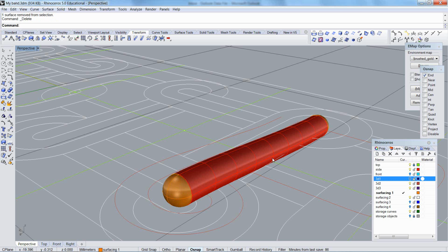That's a good trick to use, guys. When you have an object like that and you just want to keep one piece, explode it, then take out the one piece that you want to keep using control click, and the rest will remain selected, so you can just hit delete. That way I don't have to go click, click, and delete. The command of explode left them selected for me.